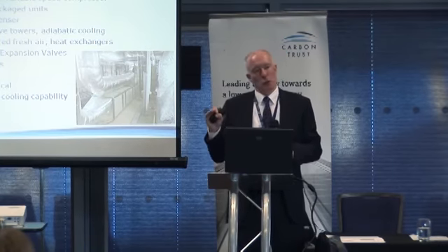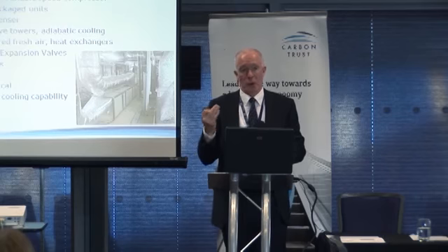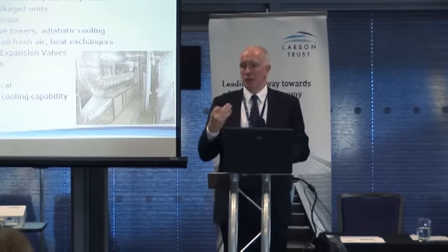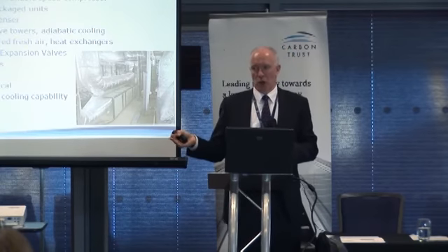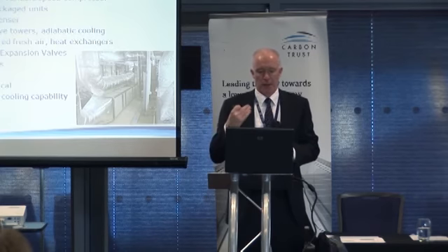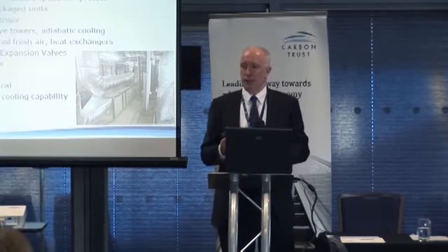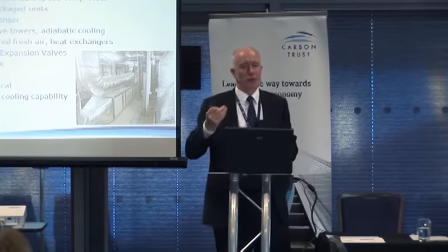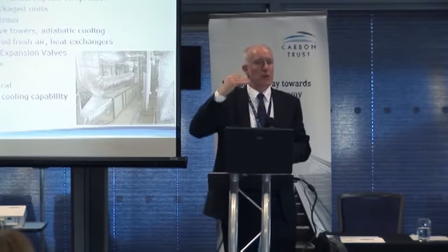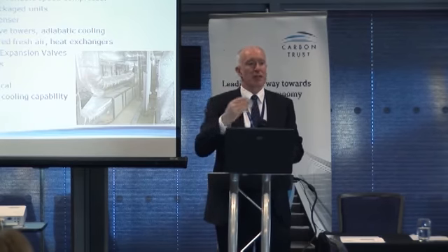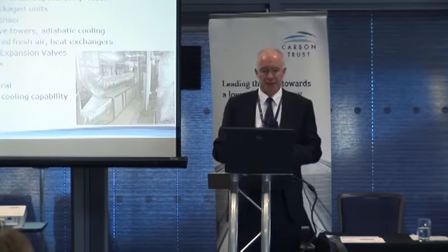People are moving to cooling water towers, evaporative cooling. I know you have problems with Legionnaires and you need to manage it very, very well, but these towers will be operating under cooling load all the time. Cooling towers work very safely across all of the globe. They're used hugely in warmer climates, so they are very safe, but they need to be managed. If you don't like cooling towers, use adiabatic cooling. This is where we put mains cold water onto the metal heat exchangers of a condenser and drip that through, and so you get the evaporative effect on the outside of an indirect system, and you haven't got a trough that can develop bacteria in it and algae, etc.